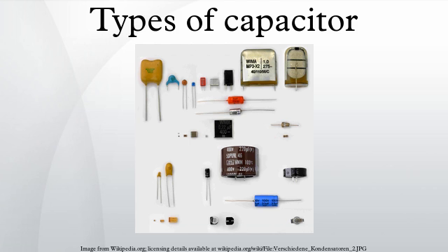To counter this potential problem, circuits frequently use multiple bypass capacitors: small capacitors rated for high frequencies, a large electrolytic capacitor rated for lower frequencies, and occasionally an intermediate value capacitor.